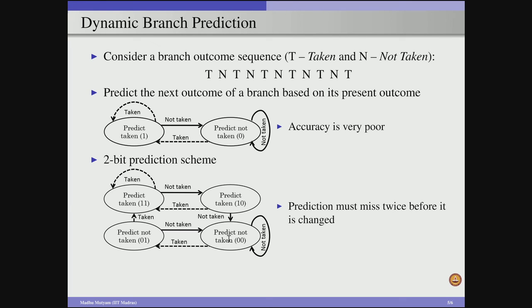And to implement these branch predictors, we can either associate a specific cache, a small cache type of thing in the processor design, where this cache will store the branch history information, branch history target, or so. It remembers the previous outcomes of the branches, and next time when the same branch happens, we index into the cache, and then based on the outcome we can take the decision. It remembers the state of the outcome.